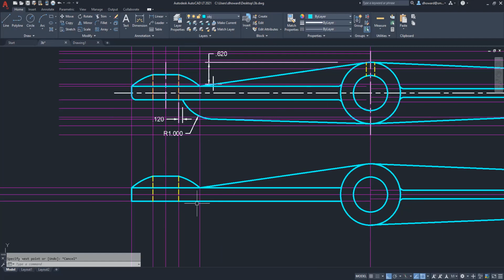Okay, last thing we got to do is the underside here. This is a little tricky. The placement of this arc is what makes it tricky. We are given some unusual dimensions that locate it. First, we are told its center point, which I have in white here, is 0.620 from the very top edge down.